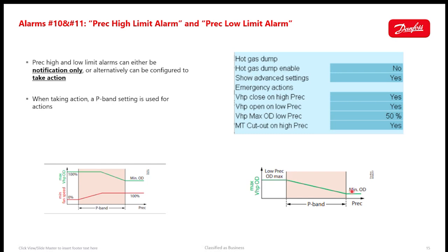So it's actually the subtraction of this. So if we're at a 480 psi limit for our minimum P-rec, and we have the 40 psi P band, we're subtracting that to put us at 440.